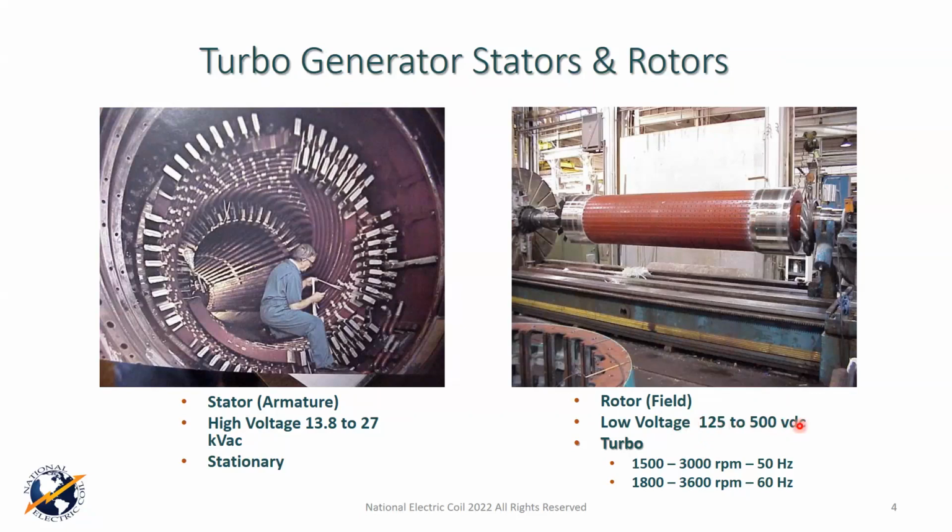There are some machines today running up closer to 750 volts DC on some of the rotors, but they're much newer and much larger units primarily. But we understand 50 and 60 hertz, we're going to have a difference in the speed that's there, but 4 poles would be 1500, 1800 respectively, 3000 to 3600 respectively for the hertz issue there.